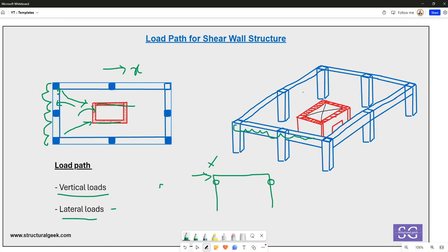If we try to understand how the load path is happening, let's say in this area you have this floor, which could be similar for multiple levels above. If the load is applied on this entire area, half of the load will be taken to this particular slab, and half of the load will be taken to the slab below. As the load gets to this slab, with the help of the diaphragm, which has much higher stiffness in plane, the load will be transferred to the supporting walls. Similarly, for seismic force in this direction, it will be taken to the supporting walls that we have.